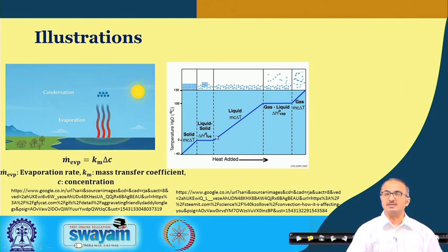Now, in this case you know that whenever there is a phase change, and here we find phase changes occurring once from the solid to liquid, and then second from the liquid to the vapor. In these two cases we find that there will not be any change in the temperature because it is happening due to the latent heat. Okay? And only during the non-phase change part, that is here and these portions, we have the sensible heat part.